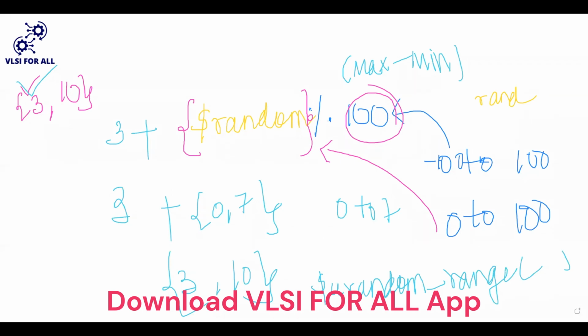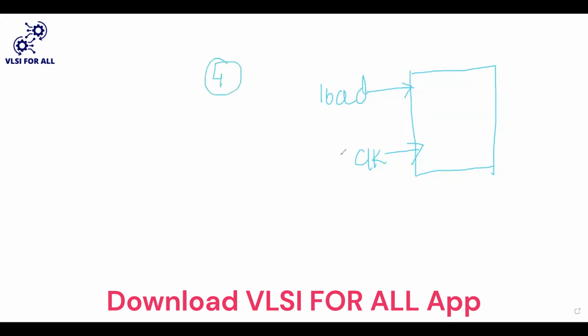And finally, the up down counter. What does it mean by the up counter and the down counter? First, let's discuss what the black box should look like. The black box is nothing but the overall view. Obviously there should be a clock signal, and there should be a chance for me to load the signal. Let me consider it's a 4-bit counter. So obviously there should be a data in value of 4 bits, and there should be a data out value which should also be 4 bits.